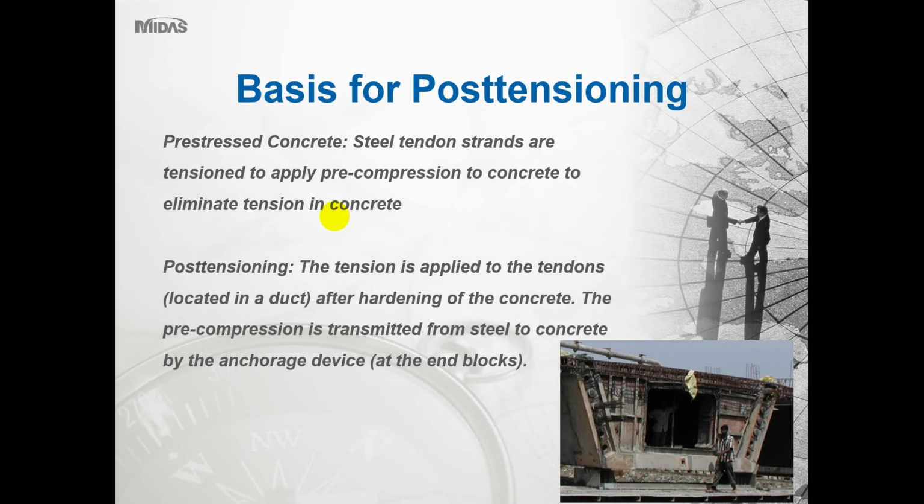So the tendon strands are pre-stressed or tensioned to apply pre-compression on the concrete, leading to effectively zero tension on the concrete section, thus eliminating the cracking and increasing the ultimate strength of the section itself. There are 2 methods of pre-stressing.